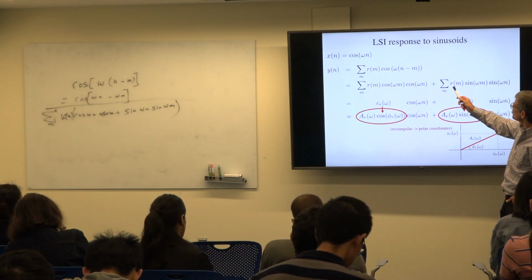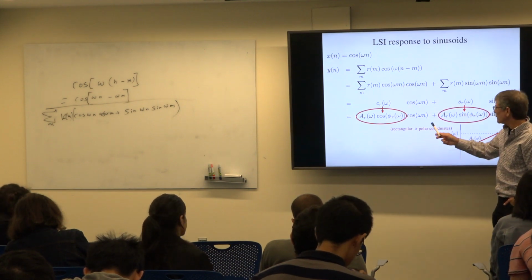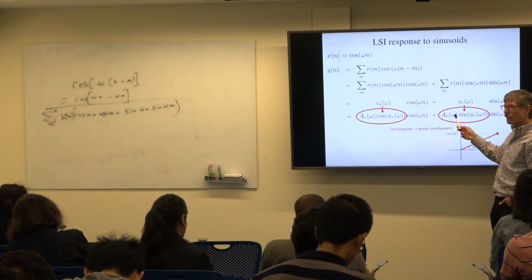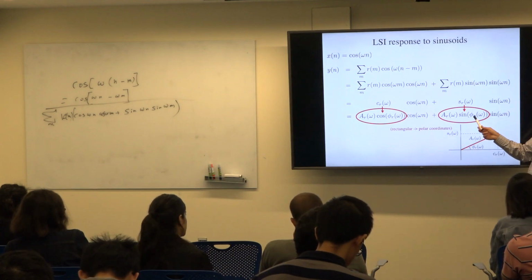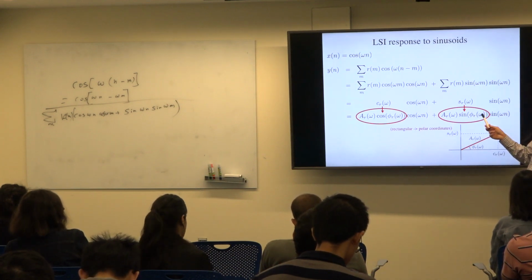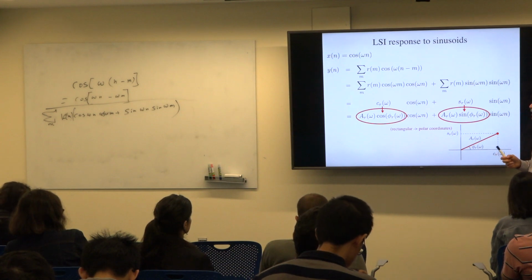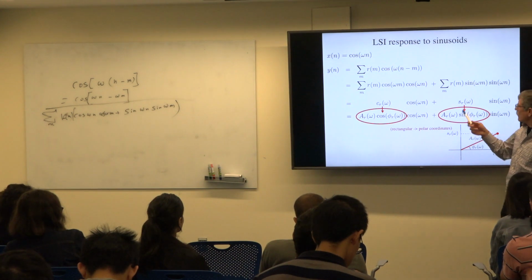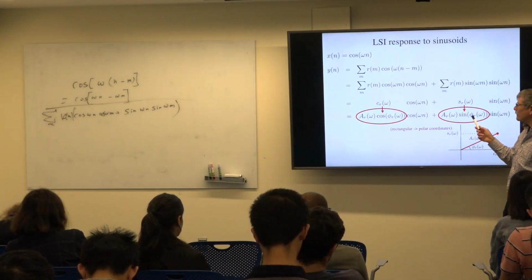Right? Here's your impulse response. Here it is being correlated with a sine and a cosine wave at that frequency. So A is going to depend on what system we're talking about, that's R, and it's going to depend on what frequency we're currently talking about, which is omega. Similarly, phi, phase delay, is going to depend on what system we're talking about, R, and at what frequency we have this phase delay. Other frequencies could have other amplitudes and other phase delays, but for the frequency that we're working with, omega, we can do the math and get, oh, that frequency gets amplified by this much and gets phase delayed by this much.